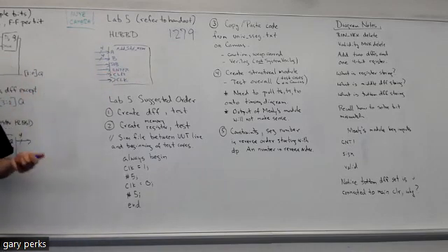Enter is the same as enable or load. Okay, when you enter, that's going to assign whatever's on input D to Q. Clear is the same as reset. So when you clear it, it's going to force the Q output to go all zeros. And then notice that set, while an input to a flip-flop, is not a main input. I'll explain why the set is necessary coming up in a little bit. Actually, it'll be towards the end of the lecture.